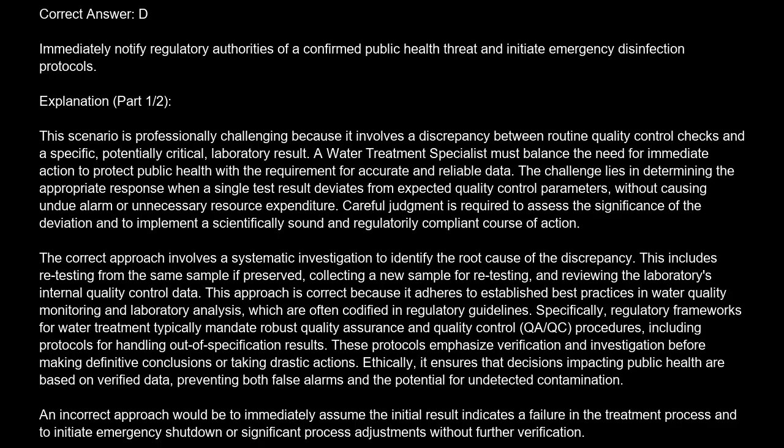This includes retesting from the same sample if preserved, collecting a new sample for retesting, and reviewing the laboratory's internal quality control data. This approach is correct because it adheres to established best practices in water quality monitoring and laboratory analysis, which are often codified in regulatory guidelines. Specifically, regulatory frameworks for water treatment typically mandate robust quality assurance and quality control (QA/QC) procedures, including protocols for handling out-of-specification results.